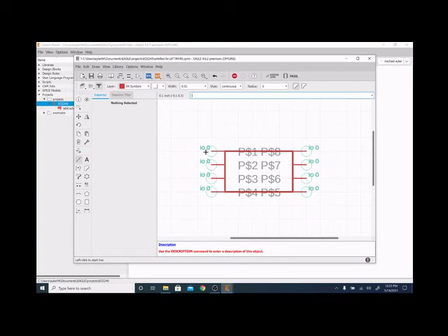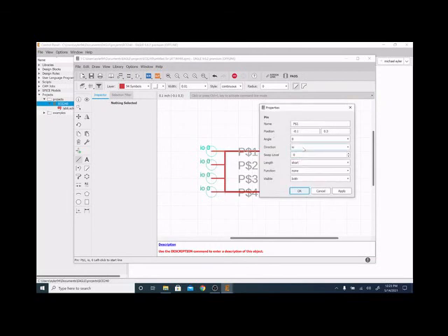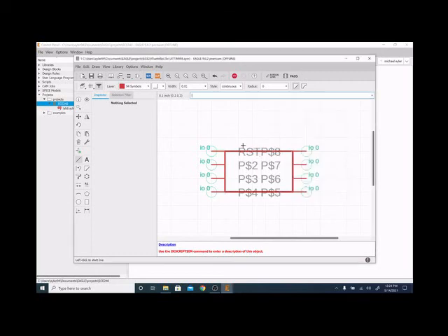So what we're going to do next is right-click on this pin, and go to Properties. This is technically an I/O pin, but more specifically, pin 1, if you remember, is a reset pin. That doesn't seem to be an option here, but because it's mostly just an input as P1, or as the reset pin, we're going to do that. So we're going to change the name to reset, set it as an input, and keep that. And then instead of visible, I really only want to see the pin name. So I'm going to hit OK, and now you can see it says reset there.